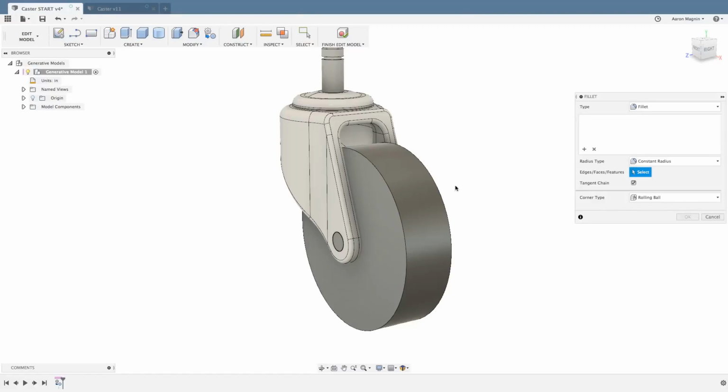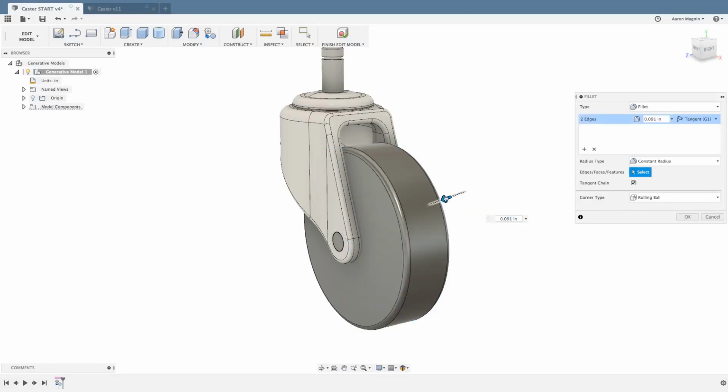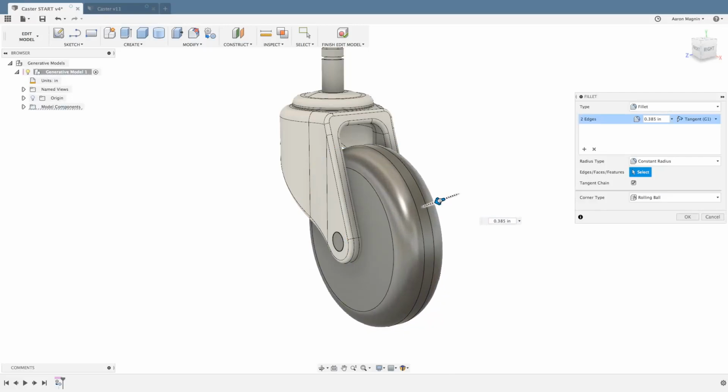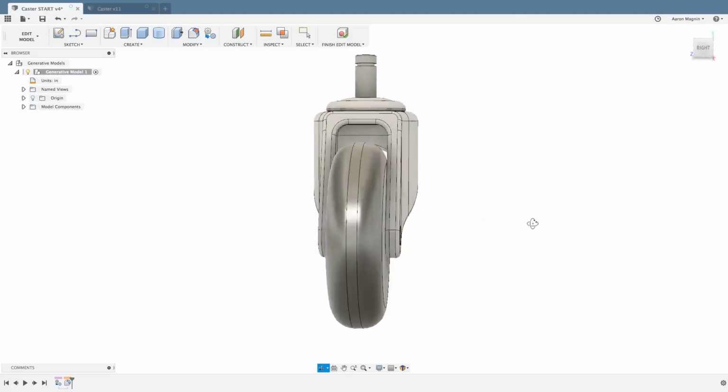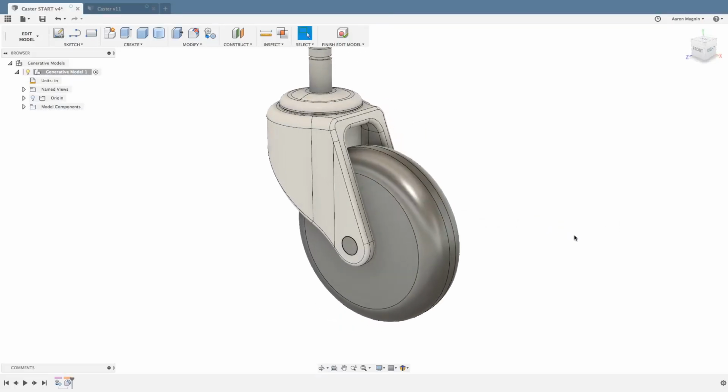If you wanted to, you can go and add a fillet in this workspace. So I'm just hitting F on my keyboard to access my new fillet command, which, by the way, there's some nice things going on there as well with the update. Make sure to check the blog and the other video that's related to this to learn more about some of those other enhancements. But I'll just pull it back in a little bit, and that's looking all right.